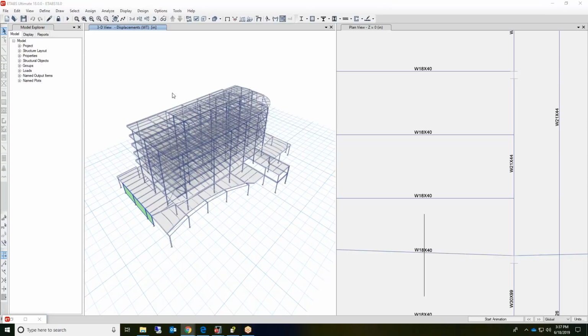Some items for efficiency have been included and updated here in ETABS version 18. Faster frame and wall design for all design codes and materials when considering many load combinations that contain multi-step load cases such as time history. Reduced size of results stored for direct integration time history load cases, as well as faster recovery of analysis results for API programming interface. Speaking of API, that is the last item on the list here for new enhancements. Starting with ETABS version 18, the API will be compatible with future major versions of ETABS. And let me show you all the new features included in that.